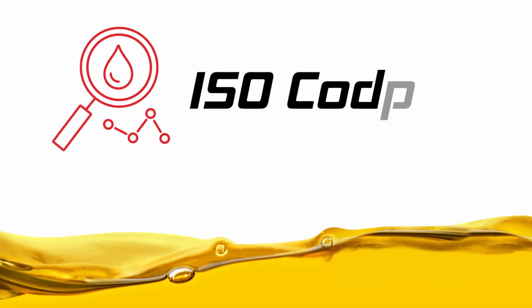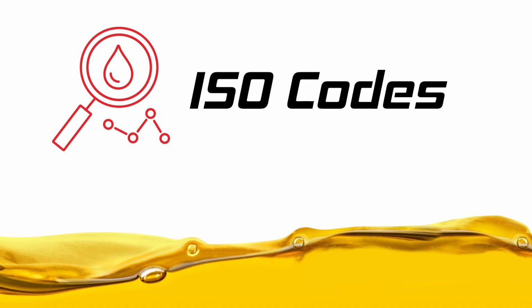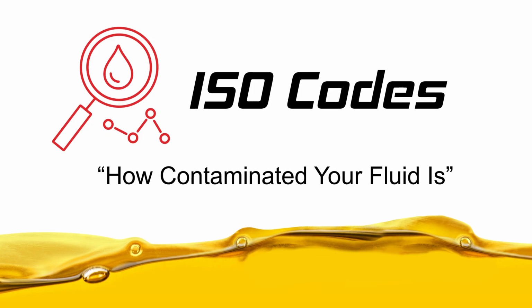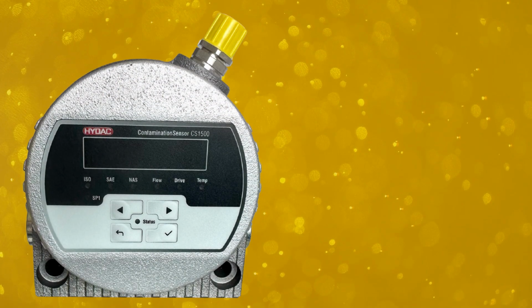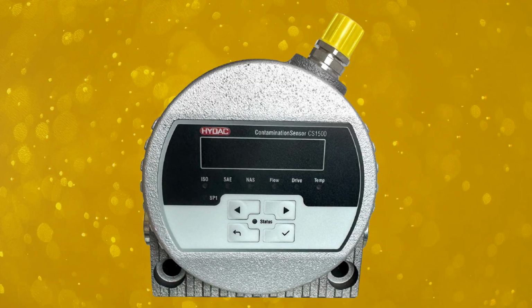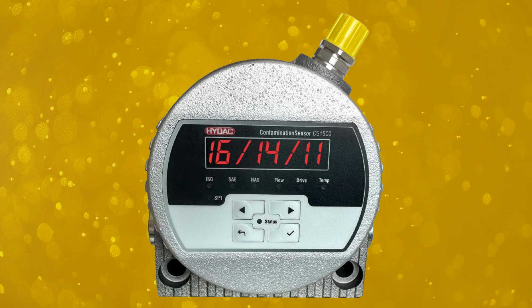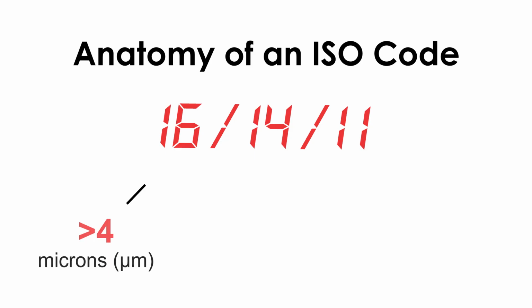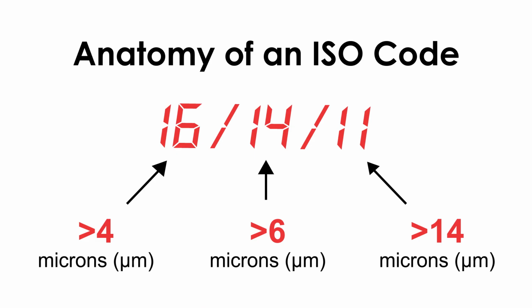Now back to ISO codes. ISO codes are basically a shorthand numerical representation of how much solid contamination is in your fluid. ISO codes are generated by specialized contamination sensors that analyze the size and amount of contaminants in a tiny sample of fluid. ISO codes consist of 3 numbers separated by forward slashes. These 3 numbers represent the amount of solid particles across 3 different size ranges in the fluid: particulates larger than 4 microns, larger than 6 microns, and larger than 14 microns.